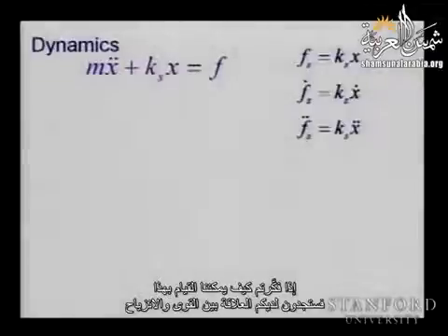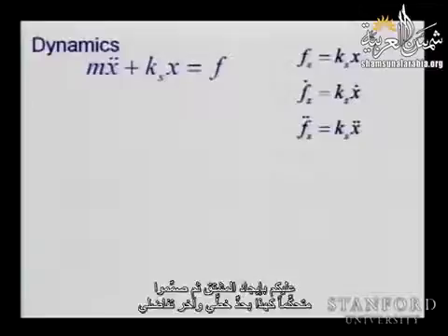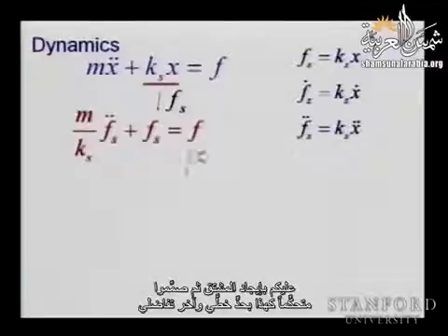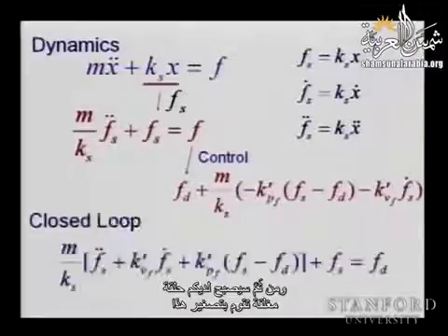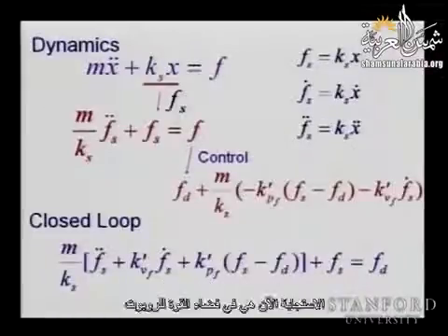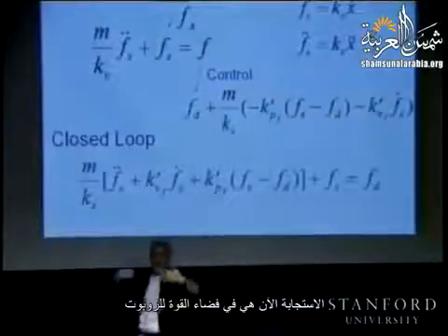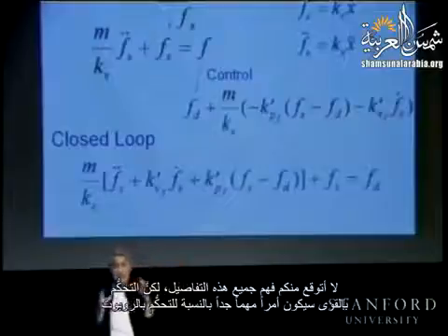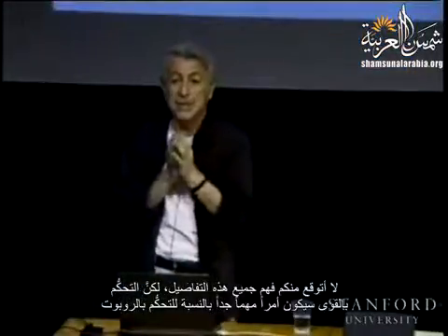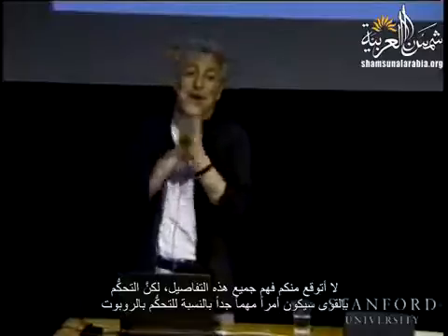So if you think about how we can do this, basically you have the relation between forces and displacement. You take the derivatives, and then you design a controller like this with a proportional term and a derivative term, and you are able to have a closed loop that minimizes this. And the response now is in force space for the robot. I'm not expecting you to understand all these details, but essentially force control is going to be a very, very important aspect of robot control.